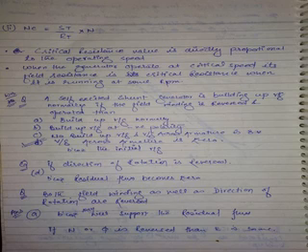Now, let us consider the generator is building up voltage normally. Let this be terminal F, and this be A. Initial condition: normally the build-up is taking place, which means the current flowing from A to F, F to FF is adding to the residual flux and the build-up is taking place. No problem. Now what is given in the problem? The field winding is reversed. Previously the current was flowing from F to FF. Now the field winding is reversed: it is FF and this is F.